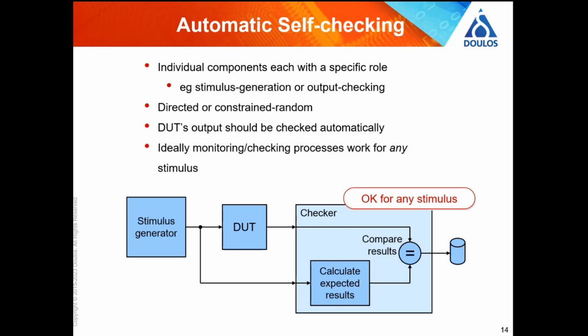But you do need one of those. You might be simulating that at the same time. What I've always done actually is run that beforehand, because for the kind of designs I've worked on, the generation of the stimulus doesn't really depend on the DUT. So you can generate it in advance and just squirt it in. And then our high-level model knew what the outputs of the DUT were supposed to be.